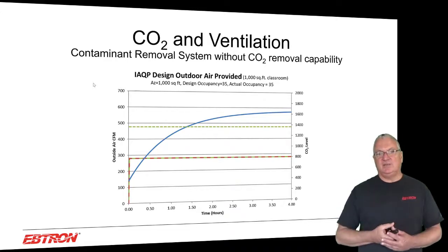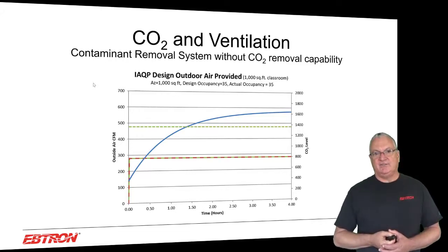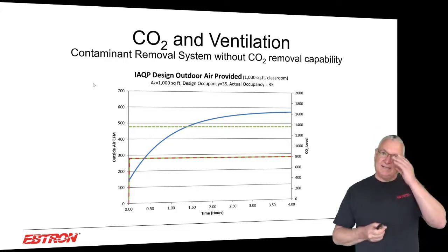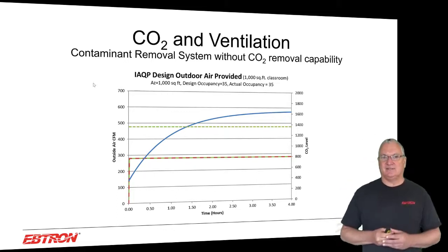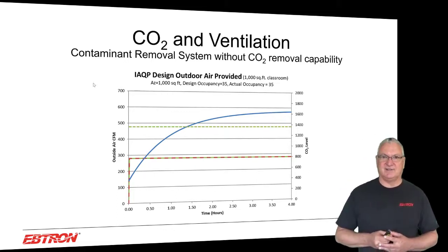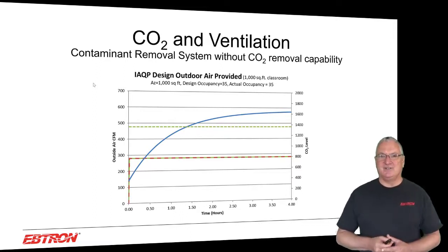Let's just say that you are operating under the IAQ procedure and you've made some claim, or somebody's told you, that you could reduce the outdoor airflow rate. Again, I personally have some problems with that, because I don't even think that Standard 62's ventilation rates are high enough for some spaces under the ventilation rate procedure, never mind reducing it using the indoor air quality procedure.